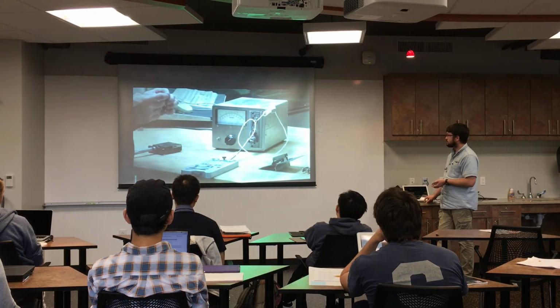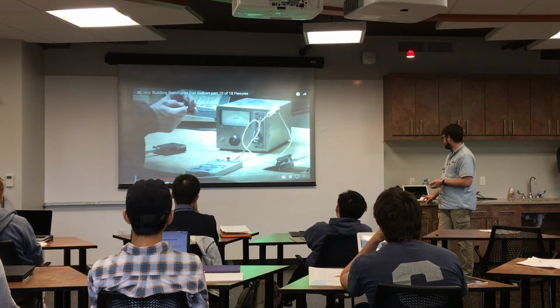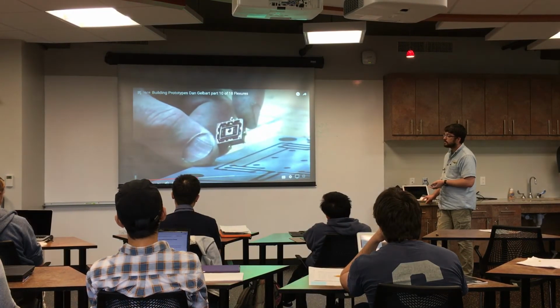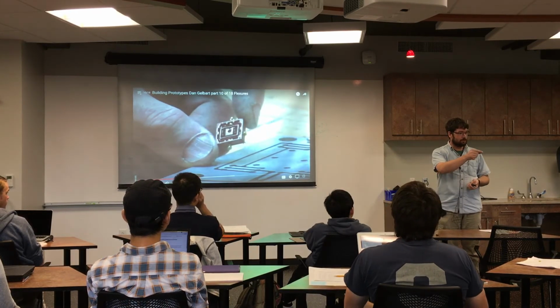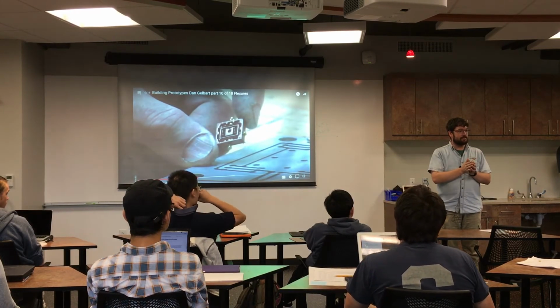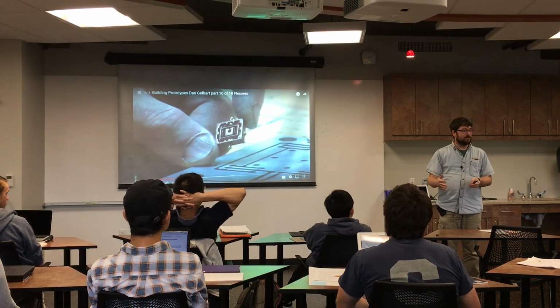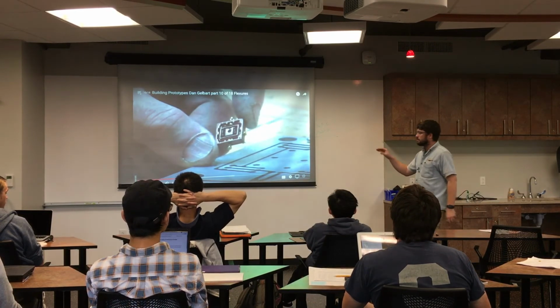Now this is an example I showed earlier. This is about as small as you can make on a water jet. Here he's got 10 nanometers control on linear motion of that stage, and it's straight to 1 micron over a range of 2 millimeters. So that's pretty incredible control and constraint of motion by using these flexures that are cut out of one solid piece.